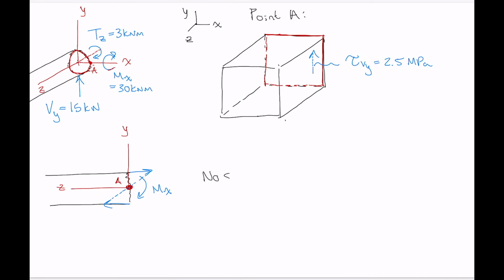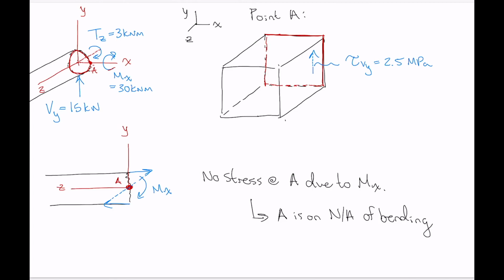So no stress at A due to Mx. And that's because A is on the neutral axis of bending for M subscript x.